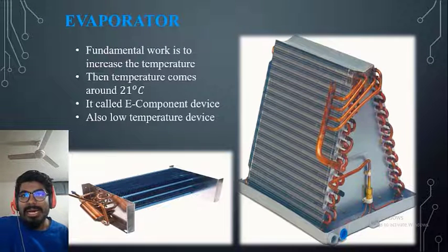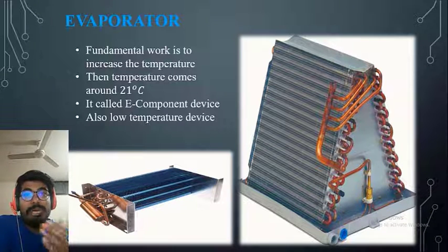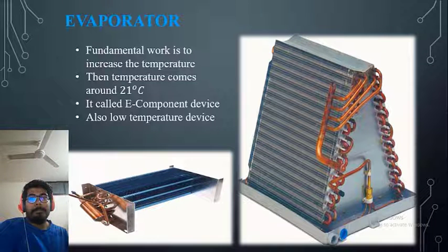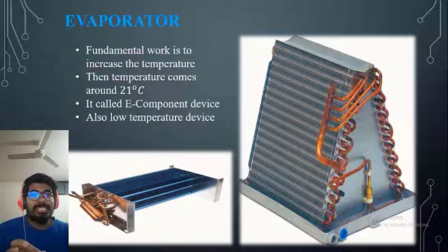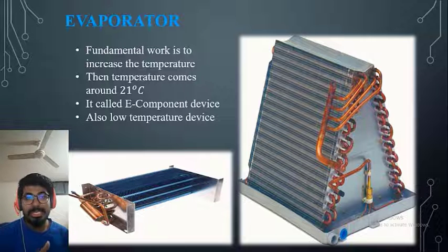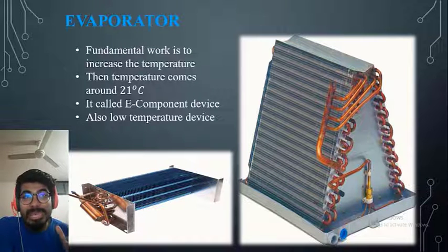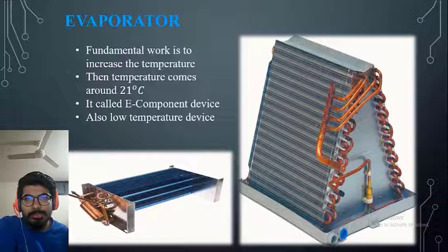Now finally, let's talk about the evaporator coil. The evaporator coil is the place for absorbing heat. When the fan blows hot air from our home over the cold evaporator coils, the cool liquid refrigerant inside absorbs the heat from the air, then continues on through. The evaporator works the opposite of the condenser.